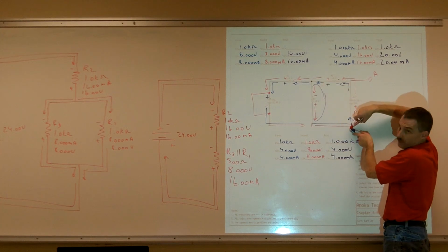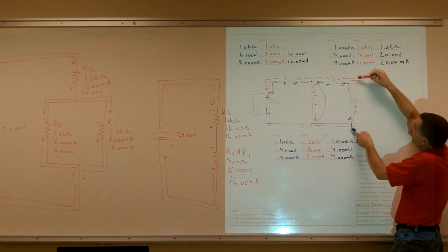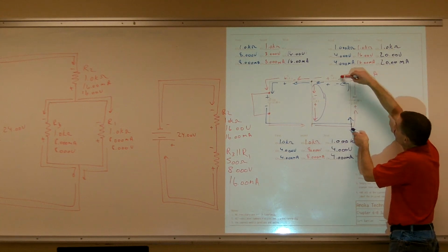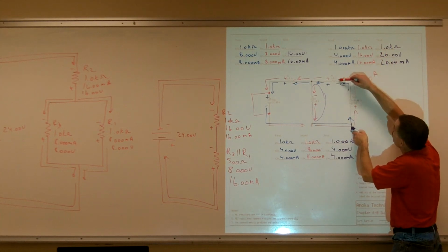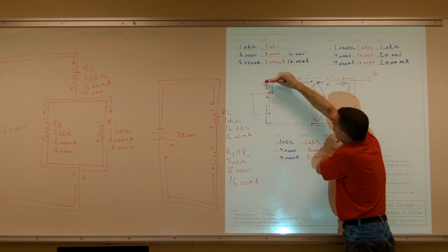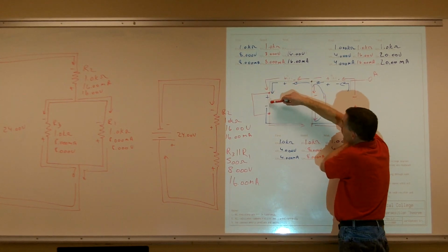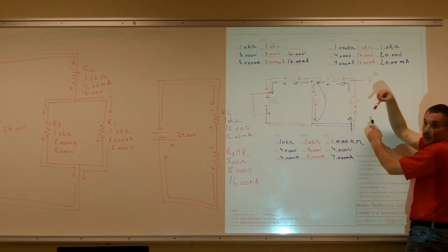Negative 4 volts. So that gives me a negative 24 volts. If I even go all the way through that other power supply, if I go from here, first sign I see is a negative 20 volts plus a negative 16, that gives me what, a negative 36 volts. Keep on going, then I got a positive 12 volts, gives me what? Negative 24 volts.